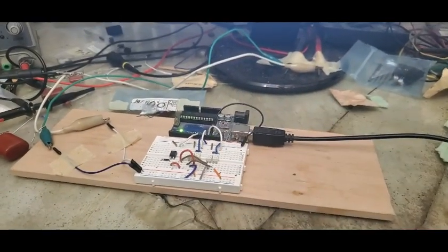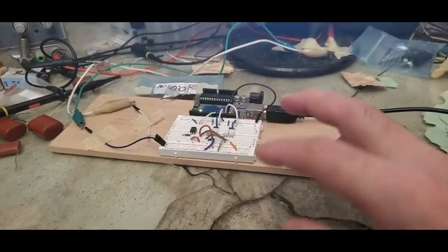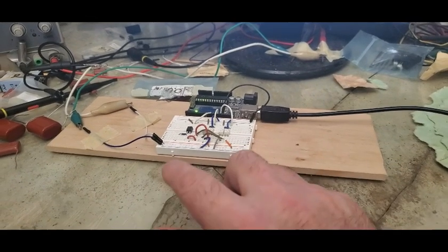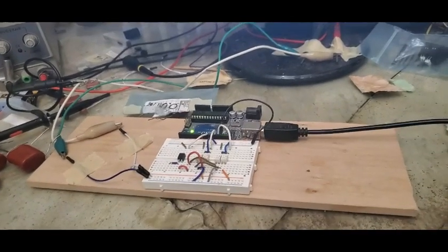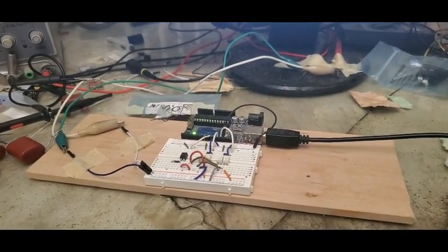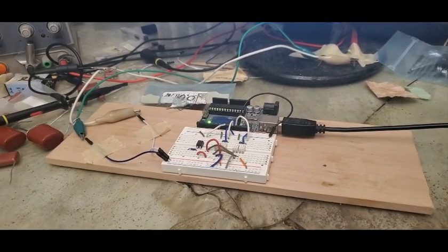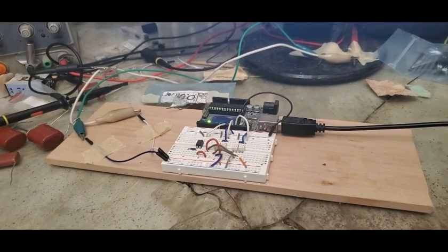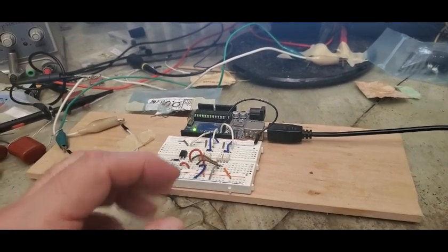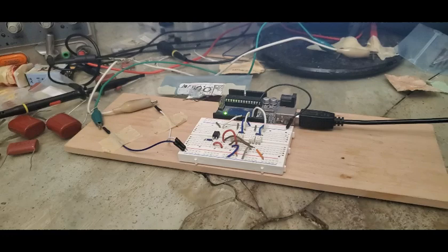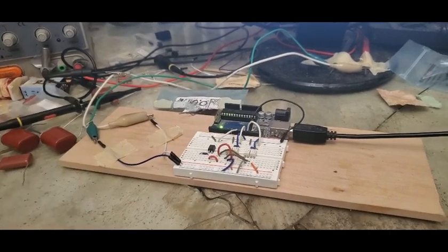And the last thing I'll show you, and then we'll wrap the video up, is, you know, there was the LCR meter, and I could see the change in resistance between 120 hertz and 1 kilohertz. And I also have some ideas for mitigating both proximity effect and skin effect. And one of the ways you see is that the Q factor should improve. But it would be nice to be able to measure things. You know, that I can look at 120 hertz, the resistance, 1 kilohertz. I'd like to measure more than that.